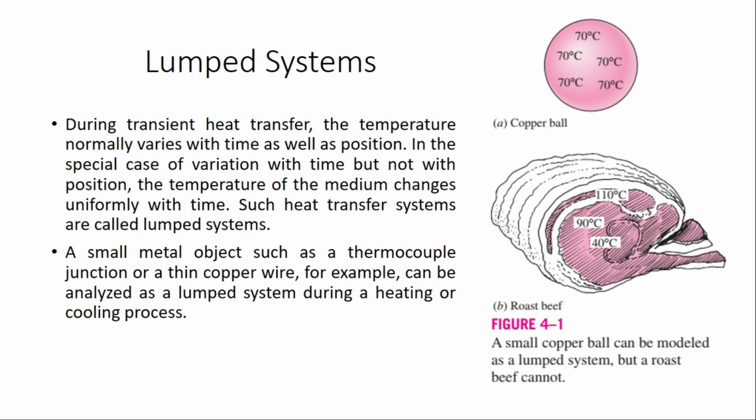In heat transfer analysis, some bodies are observed to behave like a lump whose interior temperature remains essentially uniform at all times during the heat transfer process. The temperature of such bodies can be taken to be a function of time only. The heat transfer analysis that utilizes this idealization is known as the lumped system analysis, which provides a great simplification in certain classes of heat transfer problems.